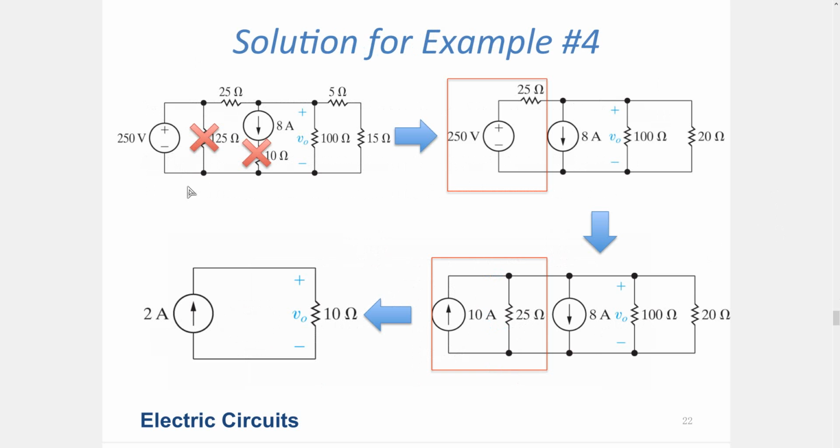So when I'm trying to solve the circuit, I can simply put open circuits in the resistors that are connected in parallel with the voltage source, or the resistors which are in series with the current source. Okay, I can omit them. Then my circuit looks like this. Now they will not affect the terminal equation. This is why I can do this.